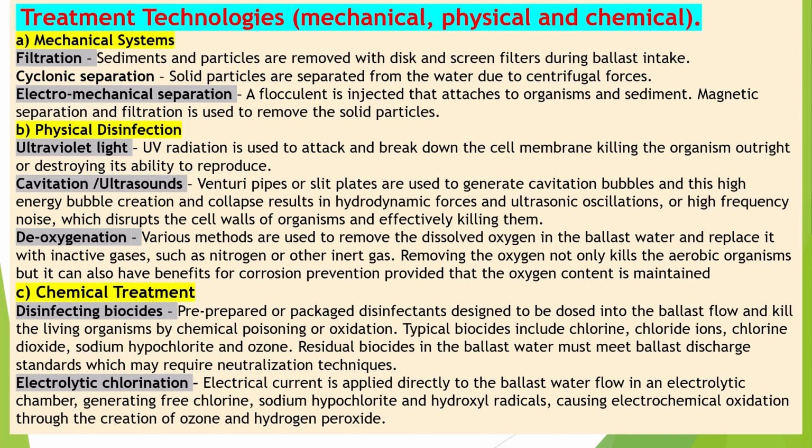Deoxygenation. Various methods are used to remove the dissolved oxygen in the ballast water and replace it with inactive gases, such as nitrogen or other inert gas. Removing the oxygen not only kills the aerobic organisms, but it can also have benefits for corrosion prevention, provided that the oxygen content is maintained.